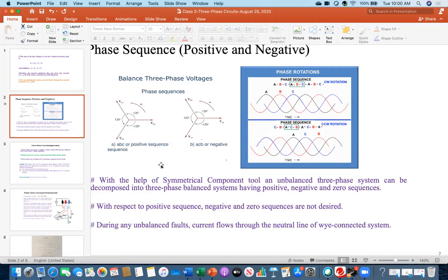So you have three points, and you want to plug this device into your system, there will be unbalance because of the phase sequence. It is not properly matching. A phase is matching with A phase, but in the United States, this is the B phase, minus 120, but in the device that you purchased from the foreign country, it has C phase here. So then that will create a problem. There will be some circulating current flow, and then either your system or that device might be burnt out and maybe damaged.